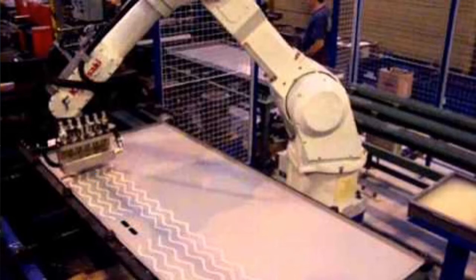This maybe is using a continuous path, but that would still be really hard to achieve that smooth squiggle. A continuous path would look kind of rough and uneven. We might have a hard time getting the robot to follow this really nice and neat pattern. So this robot is most likely using a controlled path to get this smooth, controlled, nice and even distribution of glue or printing ink, whatever this may be. So this application would need a controlled path programming style.